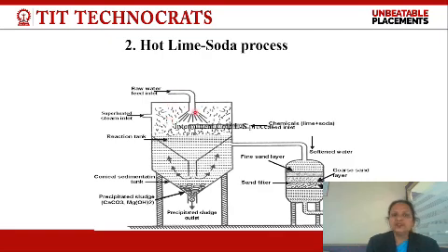When we mix raw water, chemicals and superheated steam in this chamber, the reaction is performed in the reaction chamber, and after completing the reaction, sediments collect at the bottom of the chamber and soft water comes at the upper surface, which will pass through the gravity filter. After filtering the water, we can collect it from this outlet.